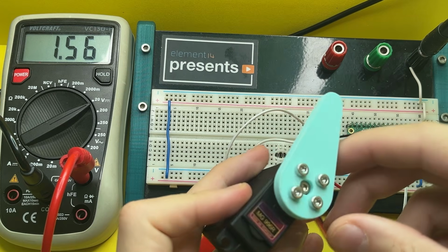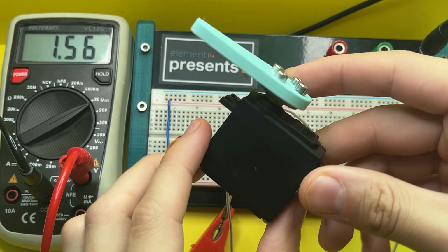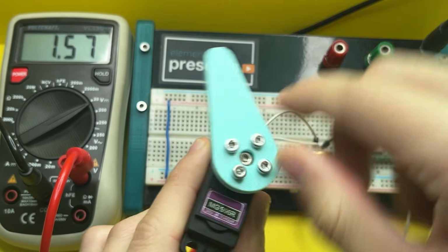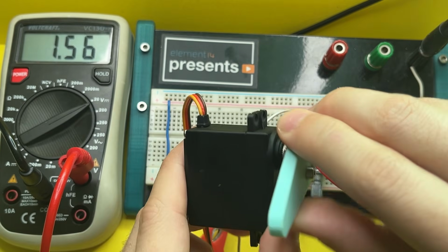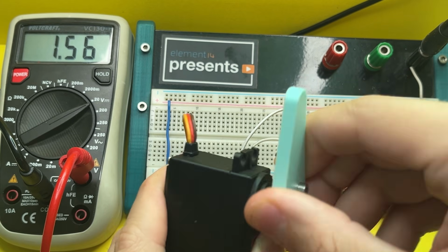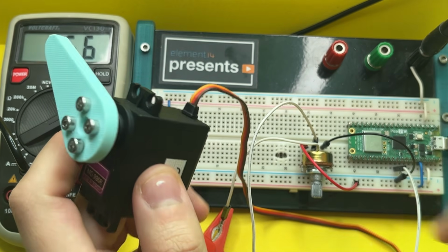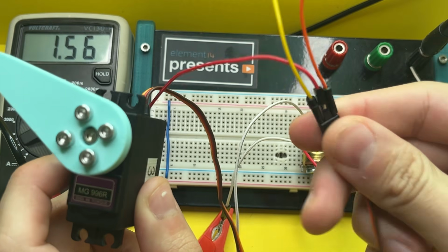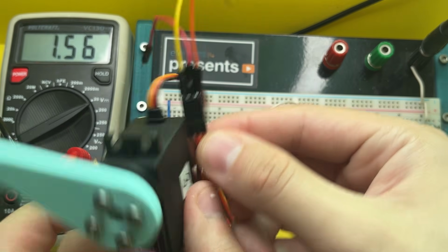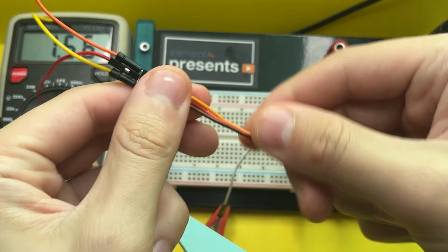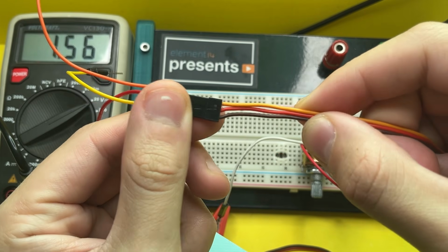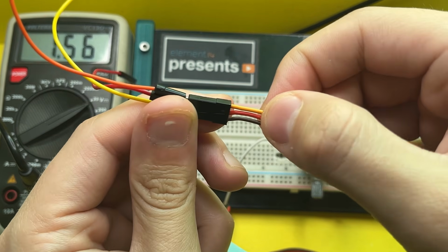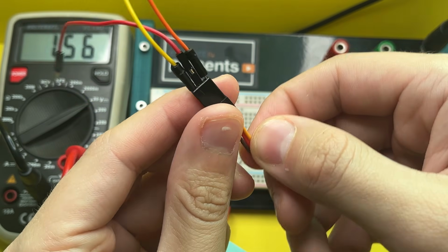Here is the actuator that we will be using. So this is just a simple servo motor, and I've attached this horn so we can more easily see how it moves. If you listen closely, you can hear a bunch of gears turning inside, and we'll check out what's happening with that later in this video. And we have 3 wires. So if you take a look at the colors here, the brown wire is ground, the red wire is 5 volts, and the yellowish wire is the signal wire.